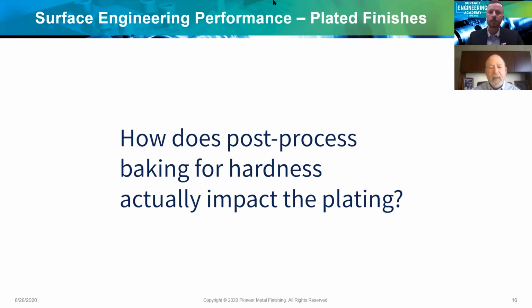Electroless nickel is an alloy of nickel and phosphorus, and it's a very uniform, crystalline type layer. When you get up to the level where you're hardening the plating, you actually micro crack it and precipitate the phosphorus out of the coating. Both of these things reduce the lubricity and dramatically reduce the natural corrosion resistance of the plating.